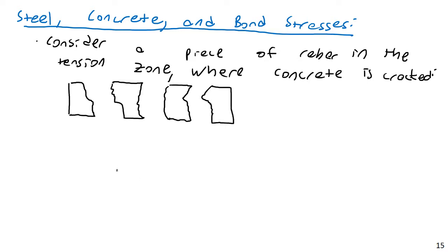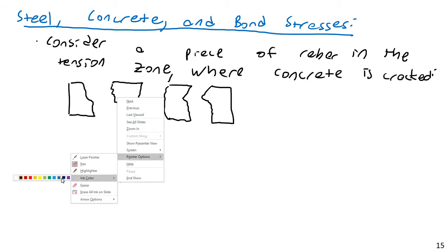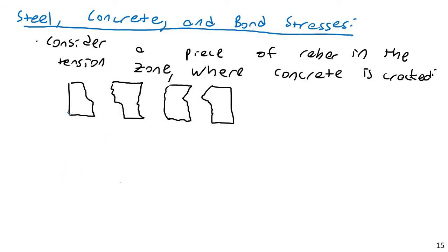And then bridging these would be a piece of rebar, connecting these. This would, of course, extend higher than this, but the tension crack wouldn't go all the way to the top. This is just a small piece of my overall depth of my beam, because up at the top you would be in the compression zone, with concrete bearing against concrete. So maybe let's do a little bit darker blue here.